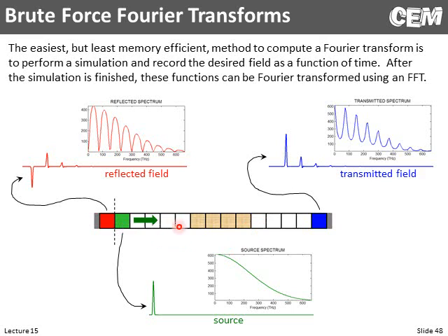So we inject the pulse, and what we see is, I'll look on the transmitted side first. We see our initial pulse, but clearly the pulse is bouncing around inside the device, and we see this as ringing. And we need to let the simulation run long enough that all of the energy has left the model. If it's very resonant, what you'll see is these ringings don't really decay that fast, and they might follow a slower profile like this, and we just need to let the model run and run until all the energy leaves. And on the reflected side, we would see something like this.